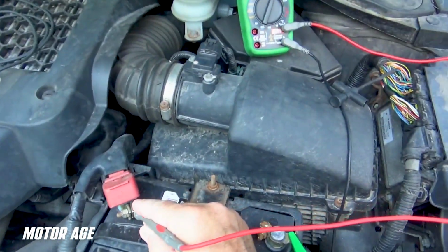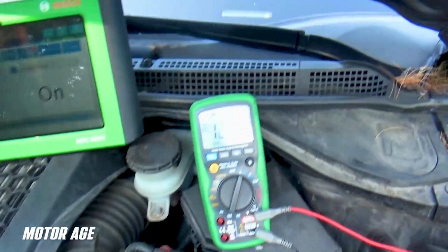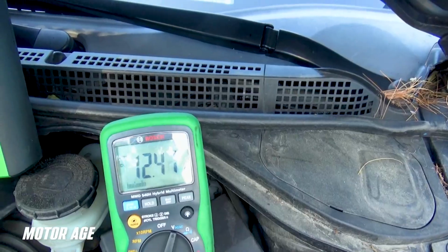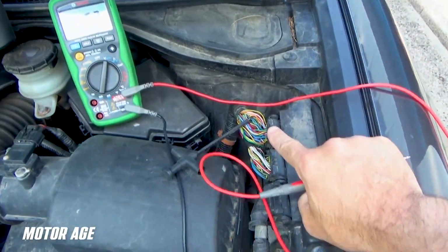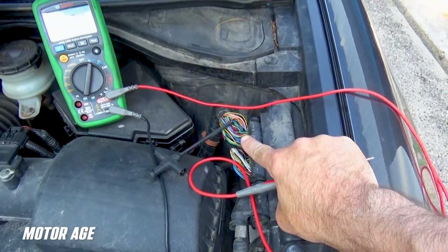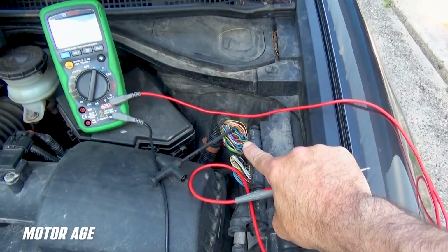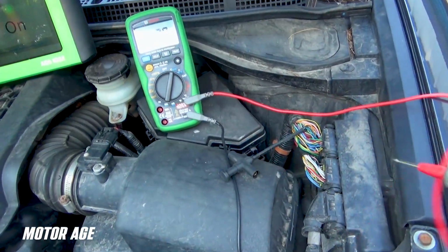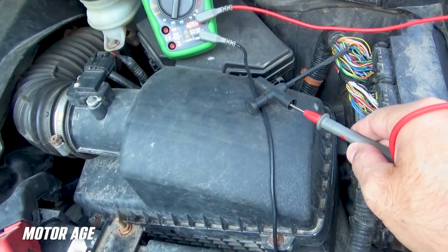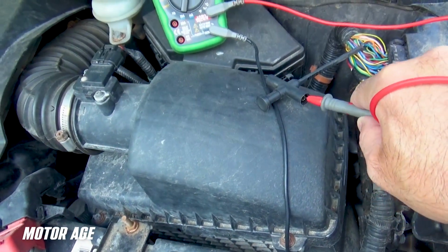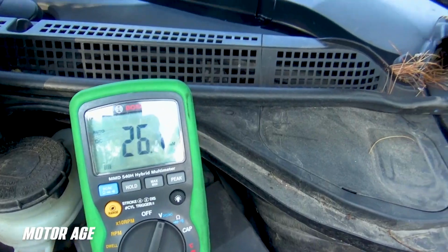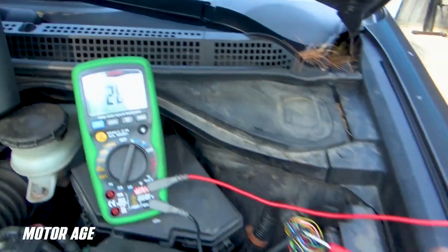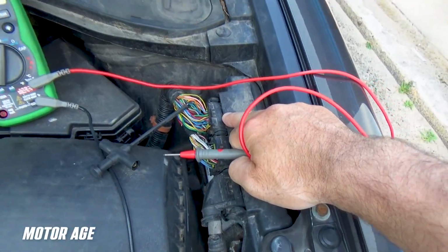Proving first that we are referenced to a good battery ground and voltage source, our meter is reporting source voltage at approximately 12.4 volts. Our VTEC pressure switch circuit, key on, engine off, as we are right now, should read voltage high because our ground reference is disconnected via the disconnected switch. But as you can see, when we touch it, we've just got several millivolts on it, indicating either a path to ground or poor output from our PCM.